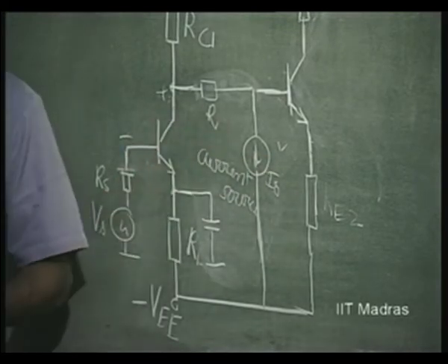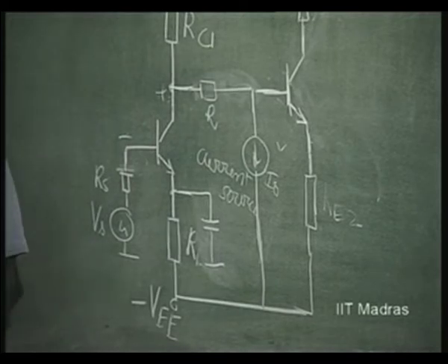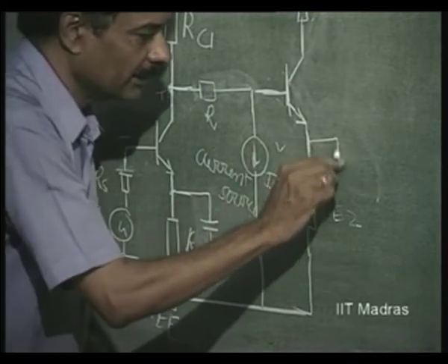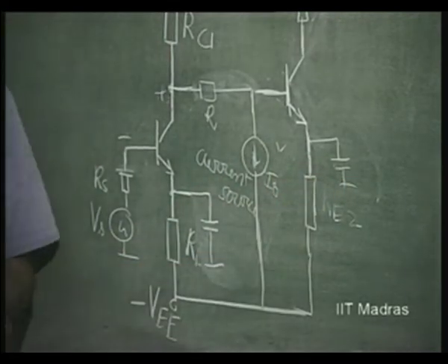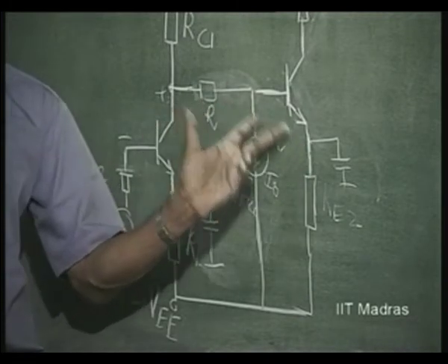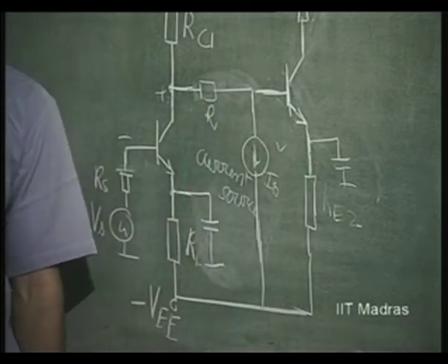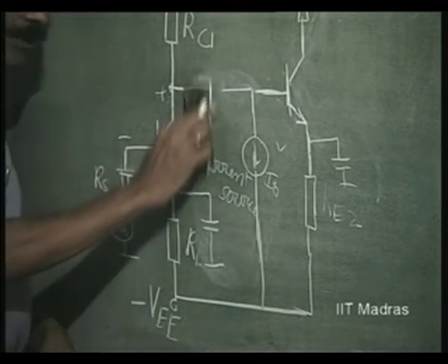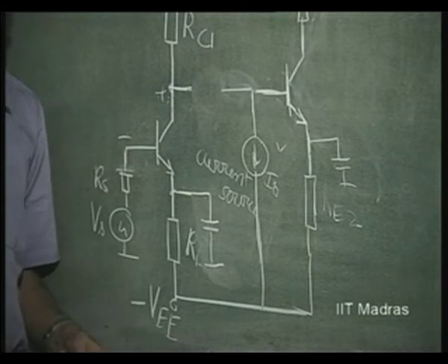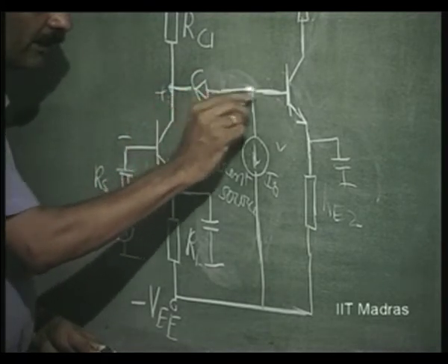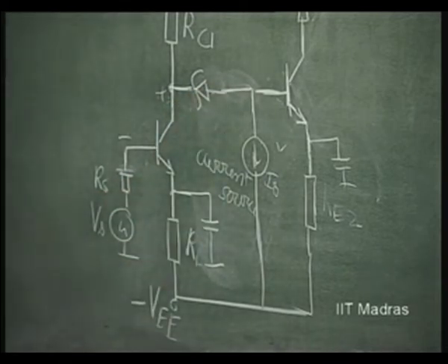This kind of putting a resistance also is not very good, because even if you put a current source, there is going to be the input impedance of the next stage, and if you put a resistance, again AC is going to be attenuated. So you have to put, instead of a resistance, a battery, right, and that kind of battery is available in circuits as a Zener diode.